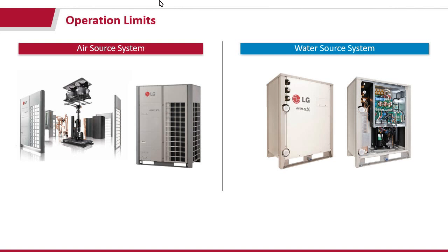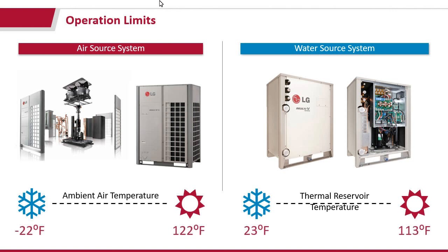So lots of space-saving potential there. And then in terms of your temperature limits, the air source units can go all the way down to negative 23 degrees now. Both Daikin and LG have developed this technology where they can do that. Some of the other manufacturers are not quite as developed, so their technology does not allow the units to operate in such low ambient conditions. But keep in mind that that is possible. You can still be in heating mode if it's negative 22 or negative 23 degrees out. It's like 22 point something, so I just went safe and put 22.